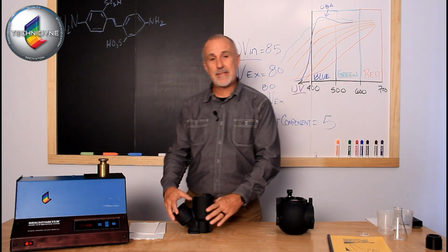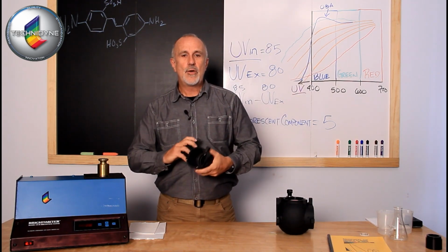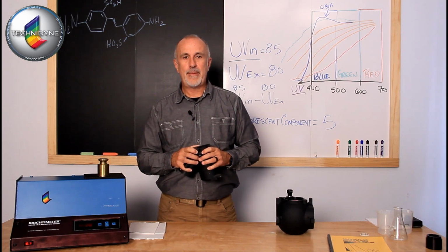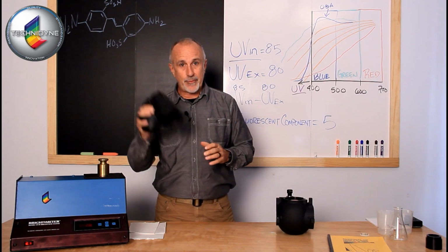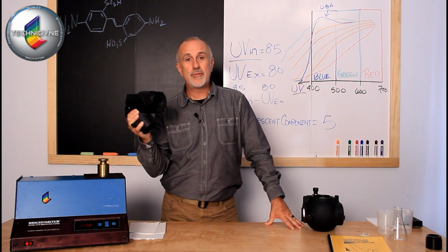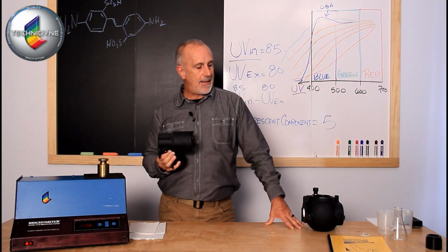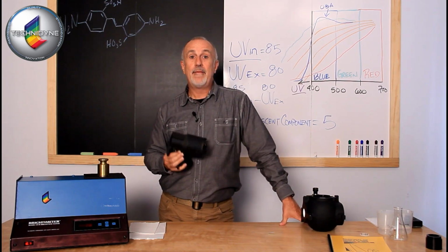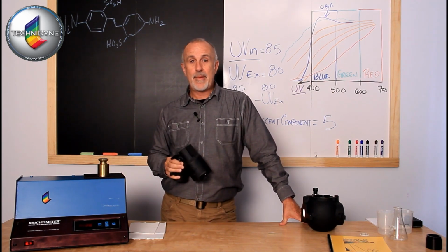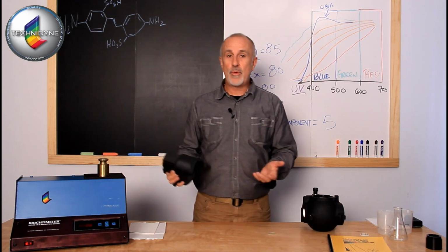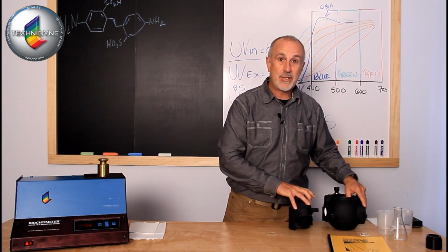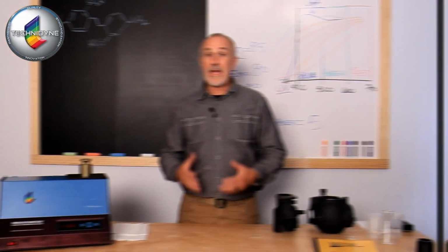Now, the benefit on this side is that there's no coating here. So a lot of our customers that have to be very particular about the control of their optical brighteners prefer to use the TAPPI method to measure the effect of optical brighteners, because it has one less variable that you can potentially have in an ISO instrument. So it's important to keep that in mind when you're making a decision as to which method to use. Okay, so that's it.